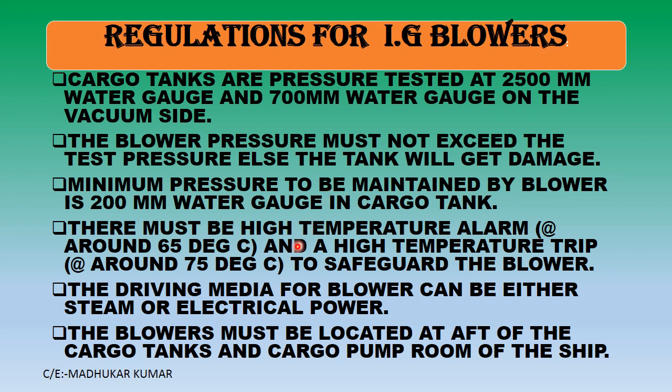Positive pressure always. There must be a high temperature alarm at about 65 degrees centigrade and a high temperature trip at around 75 degrees centigrade to safeguard the blower. The driving media for the blower can be either steam or electrical power. Both can be utilized. The blower must be located aft of the cargo tanks and cargo pump room in the ship.